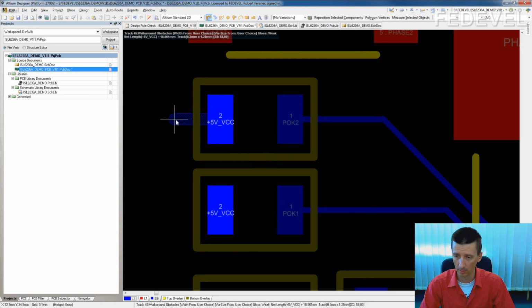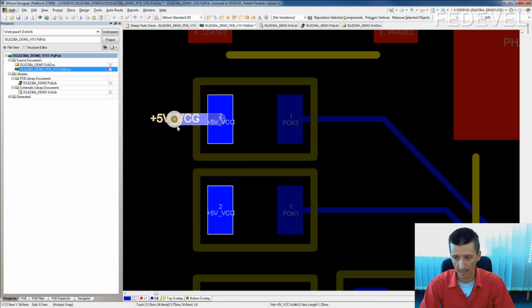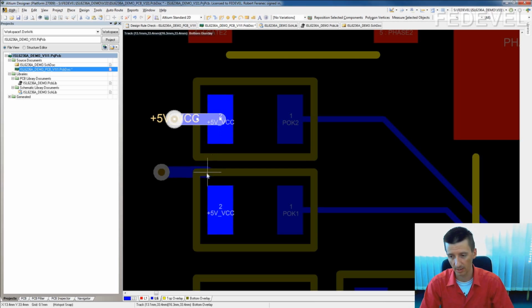Okay. Double click and then right button on your mouse. Here are the vias. Place via. And I will click here, press shift down. I will select also the via, Control C, click here. This is the position. Then when I press Control V, it will be snapped. See?